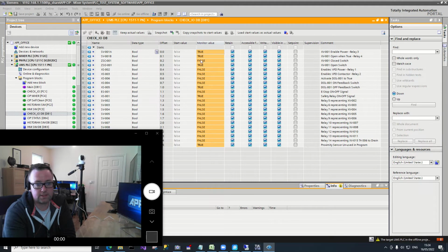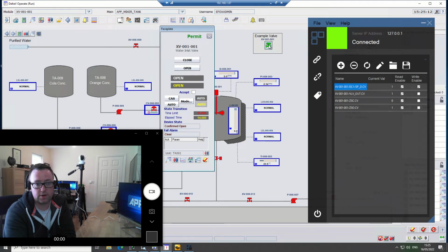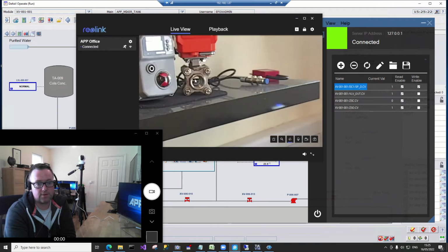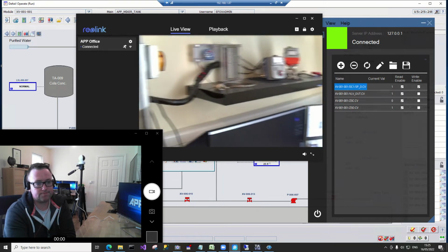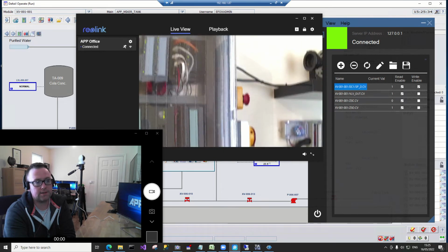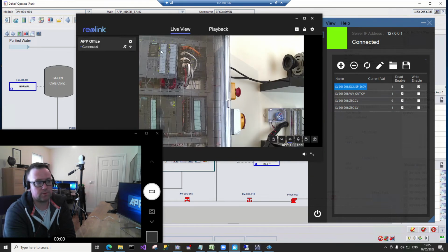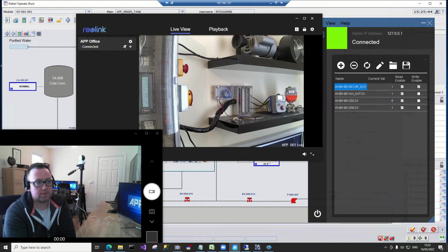So just as an example, I have TIA open, where I'm going to look at a live example and step through the verification. At the very start, what you're going to see is the screen, and I have this running, and here I have a valve that's open. I can see live here that I have this valve and it's open, because you can see right through it. If I move back here for a moment and go up a little, I have an S750 and 100, and here's the IO right here. I can monitor this IO, and if I come down for a bit and go across, then I'll be able to see my valve.